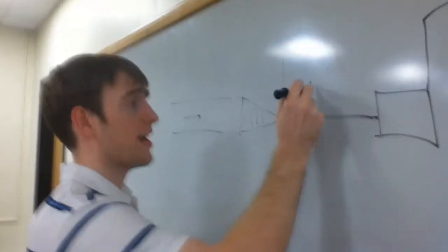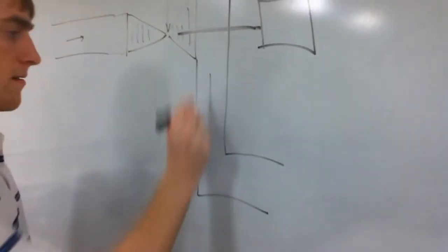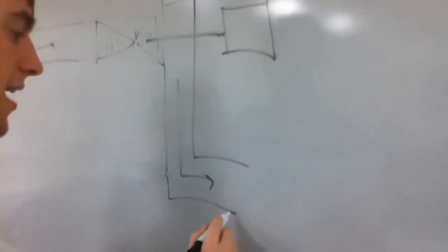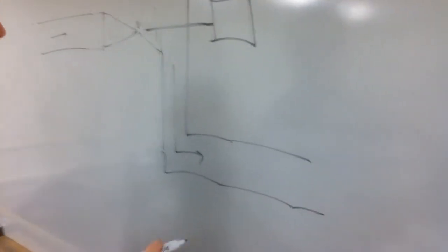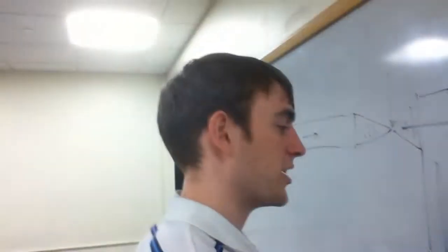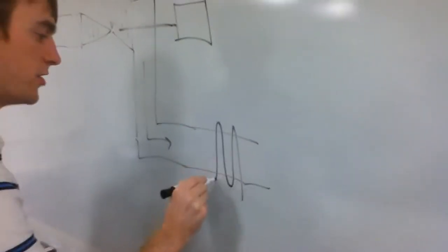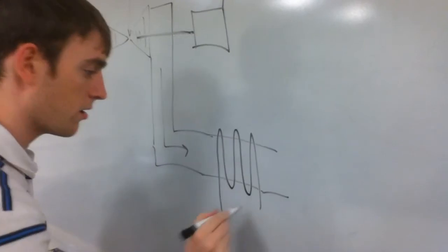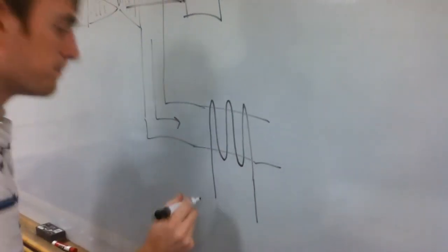Next, the hot exhaust gases from the gas turbine exit, very hot, and are passed through the heat recovery steam generator. This heat recovery steam generator is a series of tubes, much like a standard heat exchanger, which changes water into high pressure steam and high temperature steam.